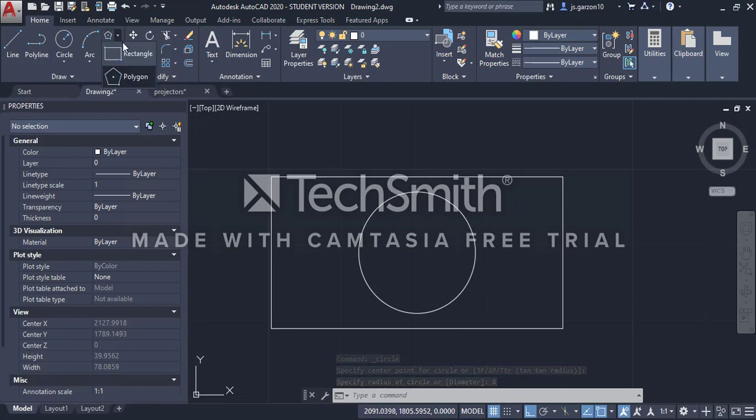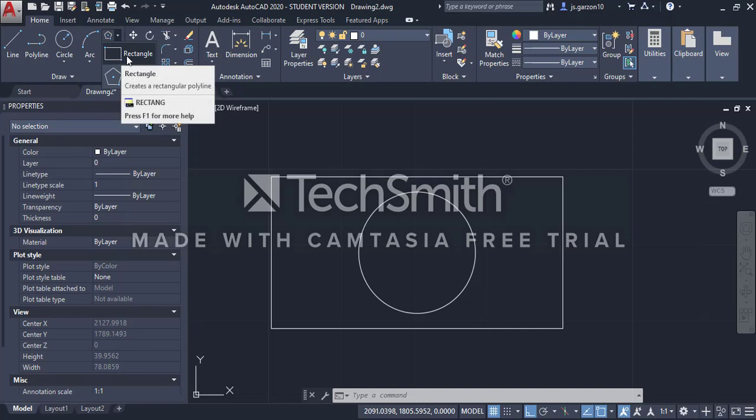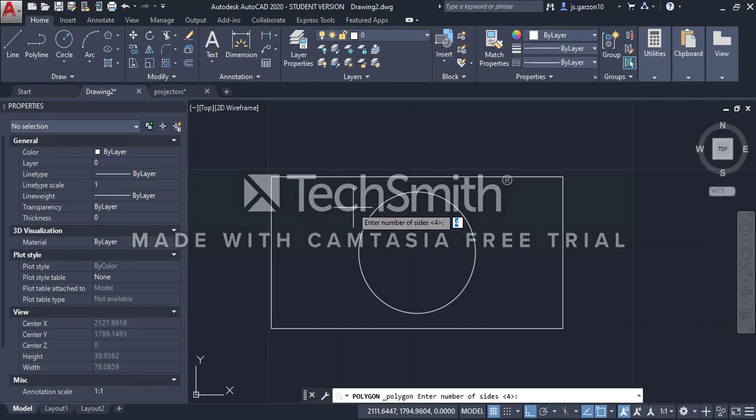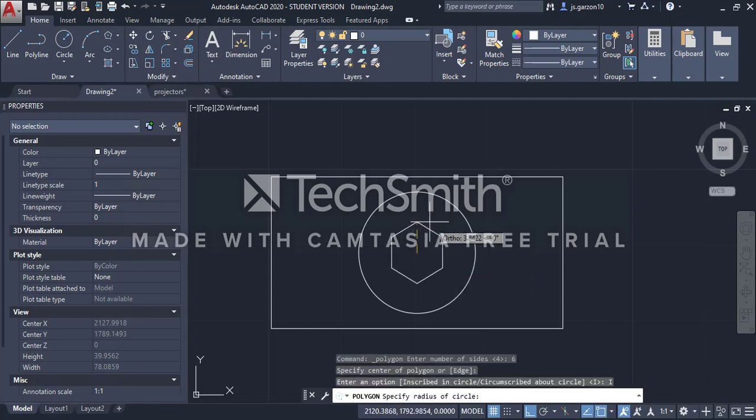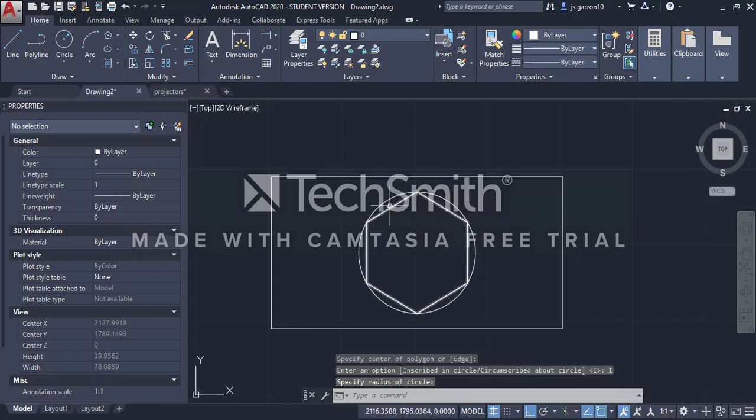With this option, you can specify a closed polygon being a rectangle or more sides, like a hexagon. 6. So first it asks you for the center. The same here, you can just click here and it will ask you about two options, being the circle inside the polygon or outside the polygon. So if you select this, you will see that the circle is at this point, the radius of the polygon. If you select the other option, the radius will be inside the polygon.